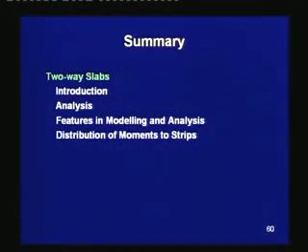The design of two-way slabs can be done by two methods. For flat slabs and flat plates, the method is given in section 31 of IS 456-2000. This method is also applicable for two-way slabs with beams that can deflect, and there is a second method which is for the two-way slabs whose beams are stiff enough and their deflection can be neglected.